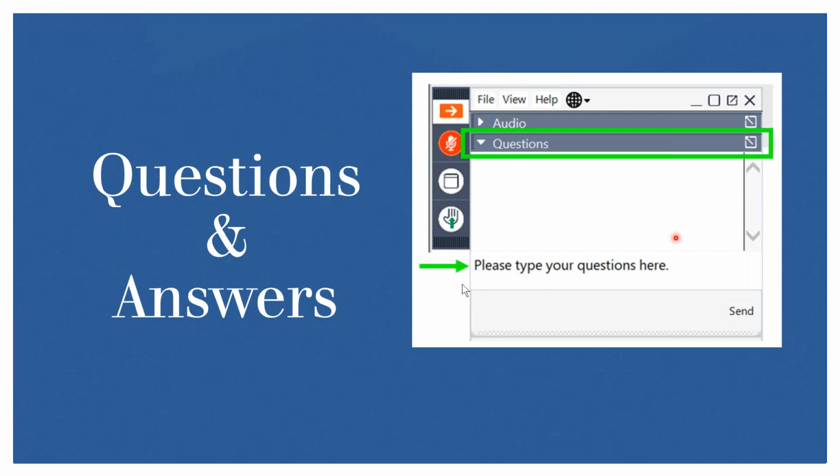So example, you are working with a spray can that has alcohol content itself, that you might smell some of the alcohol that's really pungent to your nose. The OV layer will remove that nuisance level. That's the main feature of it. If you are working above the OEL, you will still have to use a half mask respirator with filters. So we do offer the OV models, which comes with a black layer of charcoal in front.